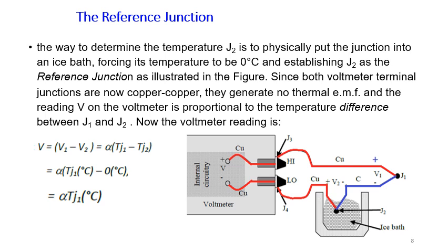So what we mean by this, let us assume that we have copper with constantan. So one material is copper and the other material is constantan. And we want to measure the voltage at the output. When we keep the constantan, which is the blue one, if I connect it to this side, it's going to cause a junction here. So this is the problem which we want to eliminate. How about the other side? For this copper, if I connect it to the terminal of the voltmeter, it is connected to copper.